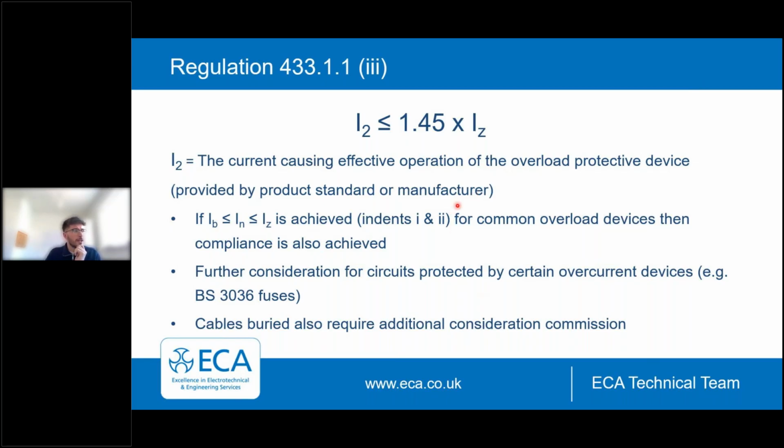So what we're essentially saying with that formula is that the I2 value would need to be less than or equal to 1.45 times the current carrying capacity of the cable for the particular installation conditions concerned, so taking into consideration any applicable rating factors.